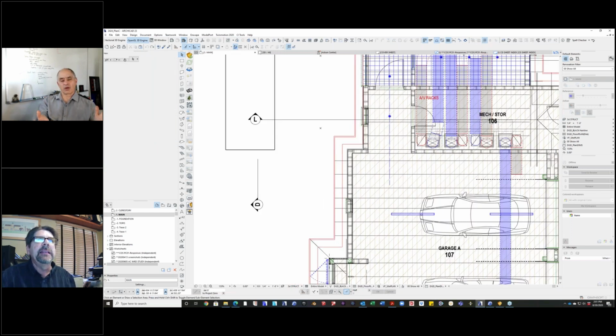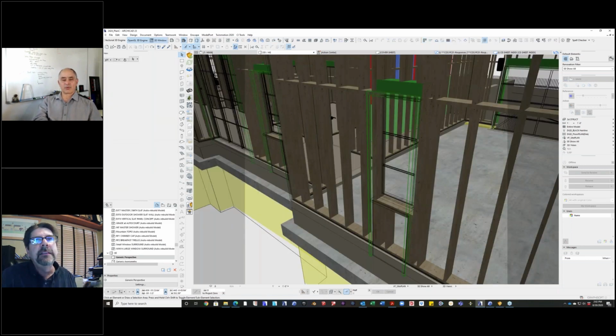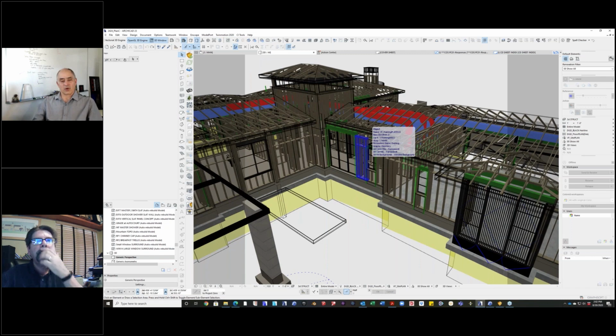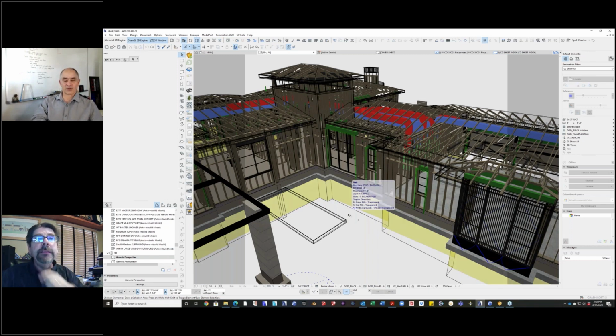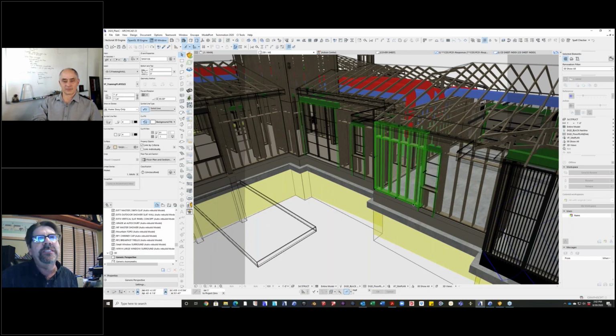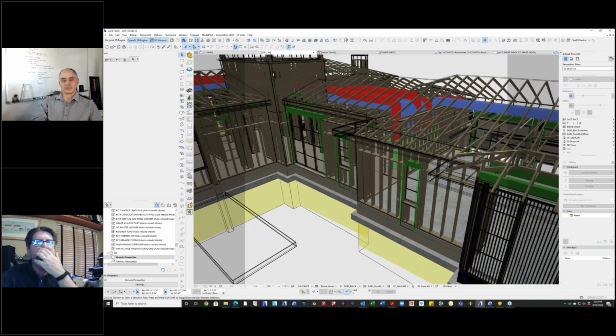You're doing semi-automatic because each one of those parts has some settings, like it's 16 inches on center, it's this dimension, do I want blocking, do I not, et cetera. Exactly. But once you've got the basic shell, you can very quickly just drop these in, stretch them, and with a few little button pushes, change it to start the framing from the right side versus the left side. Yeah, there is a shift that just shifts all the studs X number of inches, in case you have a very particular spot you want them to show up in.